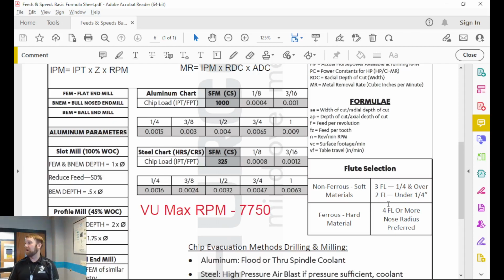When you get into smaller cutting tools, obviously the flute size is smaller as well, right? Well, they make 3 flute 1/8 inch end mills, but what you have to be careful of during the application is if you try to slot mill with them, there ain't hardly any room for chip evacuation, and it'll load up the chips in what we call galled. It'll gall up and weld itself to the tool, and then it'll break the end mill. So with a 2 flute end mill, we're limited on how fast we can feed it, but there's less of a chance of us breaking it. When you get up to 1/4 inch and above, you've got a big enough tool that the chips can get out of there. Okay, that's a subjective thing to me.